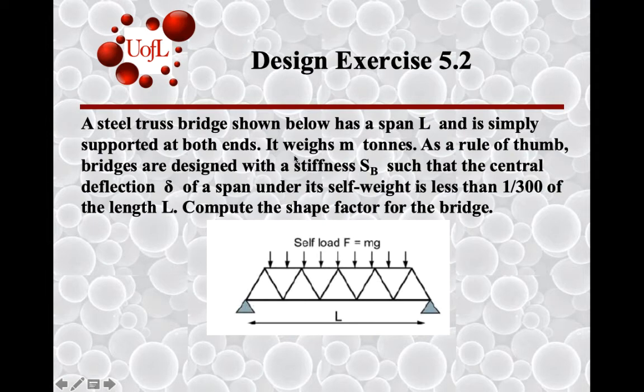And typically, these designs are designed for stiffness, so that the central deflection under self weight is 1/300th of the length. That's a typical construction engineering, bridge engineering shape factor. I think of my uncle who passed away recently, who was a bridge engineer for the railways in India.